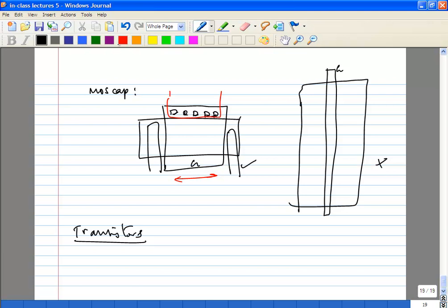do your floor planning. For example, this may be your signal, but the extra space you have may only be here. Why? Maybe your signal input is coming here, output is going here. You could perfectly well have a case like this. So if you have something like this, where would you place the bias? You can split the bias transistors. As long as they are laid out in an array internally, you can have some decent matching. You don't want to spread it out too far, but you can work around it. Or for example, you may split your bias like this. This may be cap. Cap, you can spread around, and that's usually perfectly fine.